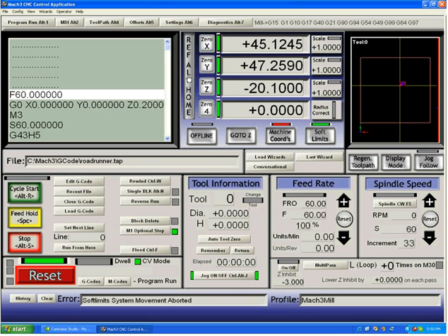The system is careful about two things in particular. One is the value of your machine coordinates. The other is the value of a DRO. The DROs are kept separate from Mach3 in code of their own. When you see a count in a DRO, it means the system has put out that number of pulses. It's a very important debugging and troubleshooting tool for me.